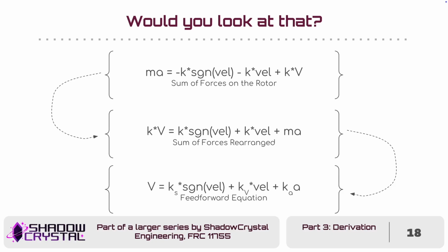And this is the basis for why the feed-forward equation works. You don't get told this as often as you should, in my opinion. The WPILib docs don't provide for this, because this derivation is why the feed-forward equation works, because it is just derived from the net forces exhibited on a motor. And once you realize that, each one of these terms starts to click, and you really start to understand why the feed-forward equation is what it is, and how to actually solve for these constants and apply it to your control algorithms.